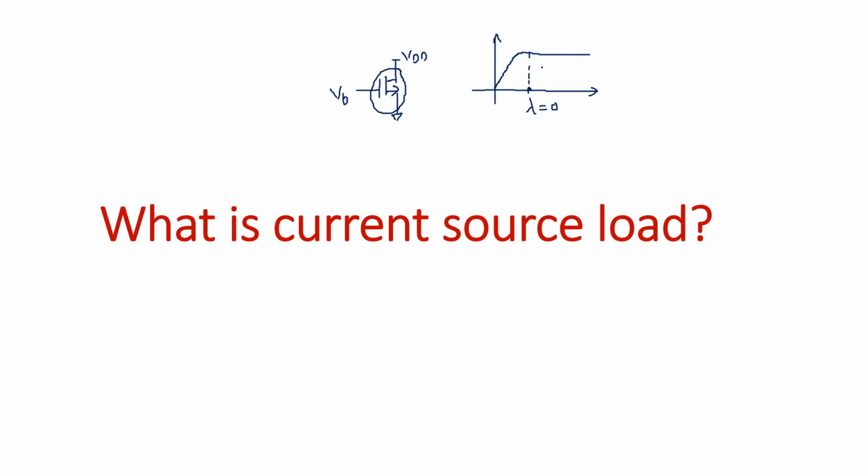after this particular value of input, in this region, the current is constant. So it is acting as a current source. So if this characteristic is ideal, means there is no slope. If there is no slope, this device will offer infinite impedance. Ideally, this characteristic is existing, but practically this is like this.